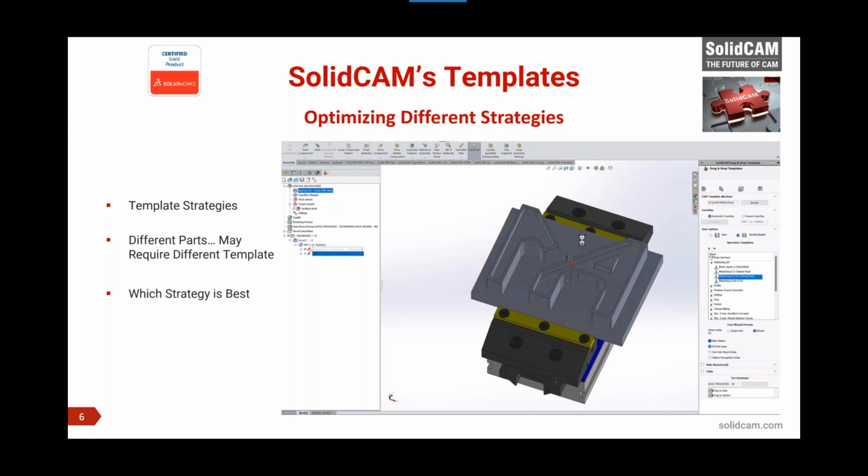We're going to see something a little bit different this time. Again, SolidCAM is very quickly going to calculate this toolpath and generate the tool motion. And you'll see in this case that it's a little bit different than what the other one was. Now it's using what we call a D-slot trochoidal repositioning strategy in encompassing that entire area. Now, if we look at the time here on the tree, we'll notice 2 minutes and 8 seconds on the first one and 1 minute and 51 seconds on the second one.